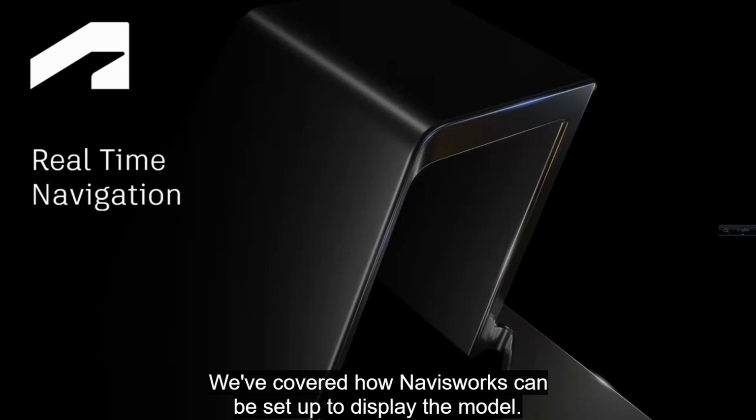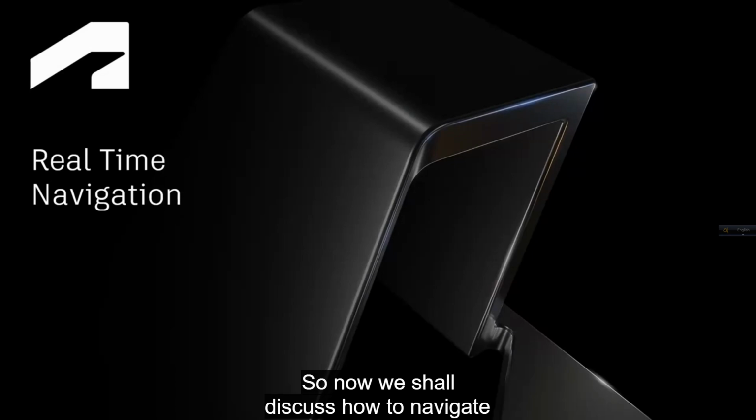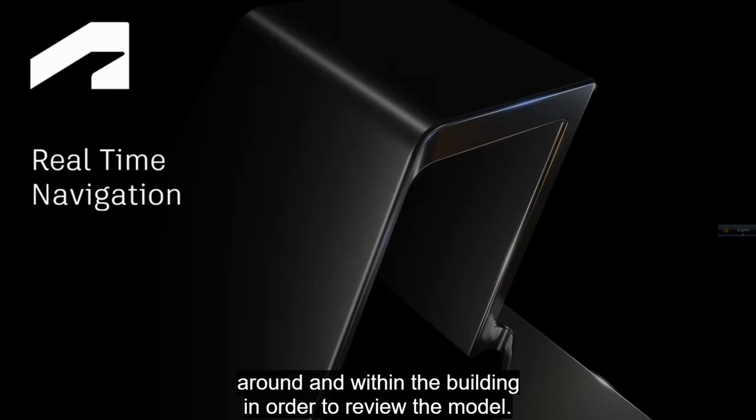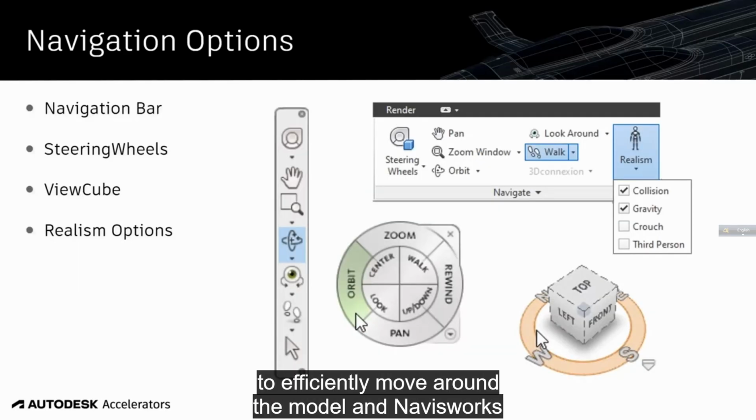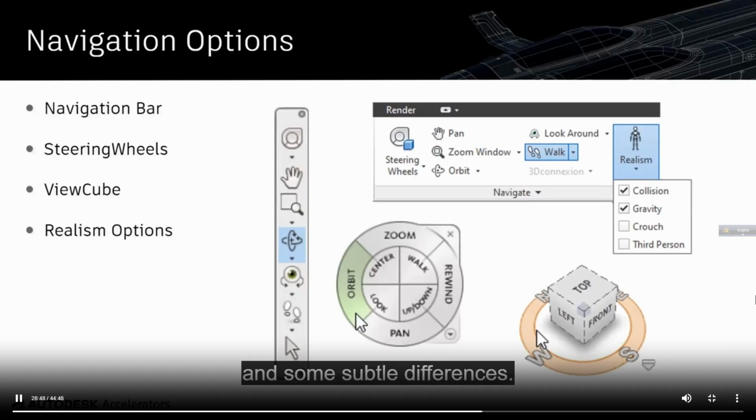We've covered how Navisworks can be set up to display the model, so now we shall discuss how to navigate around and within the building in order to review the model. A necessary part of model review is to efficiently move around the model, and Navisworks provides 3 different navigation options, which you use will be down to personal preferences and some subtle differences.